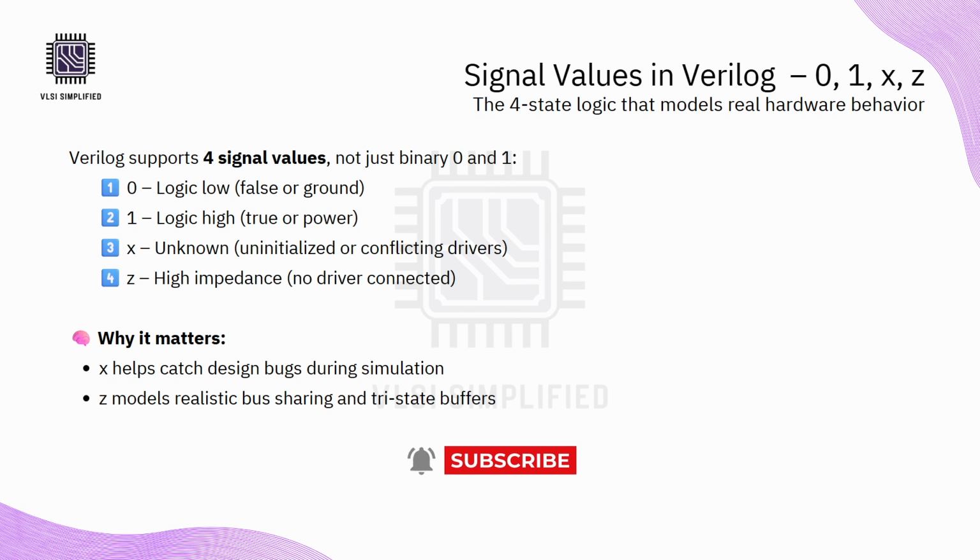So these two special values, X and Z, are really helpful for debugging. For example, if your simulation shows an unexpected X, it's a sign that something went wrong. Maybe a signal wasn't initialized properly or you forgot to assign a value in some logic path. And Z is used when we want to model a shared bus or tri-state drivers. So we will look at that in action very soon.